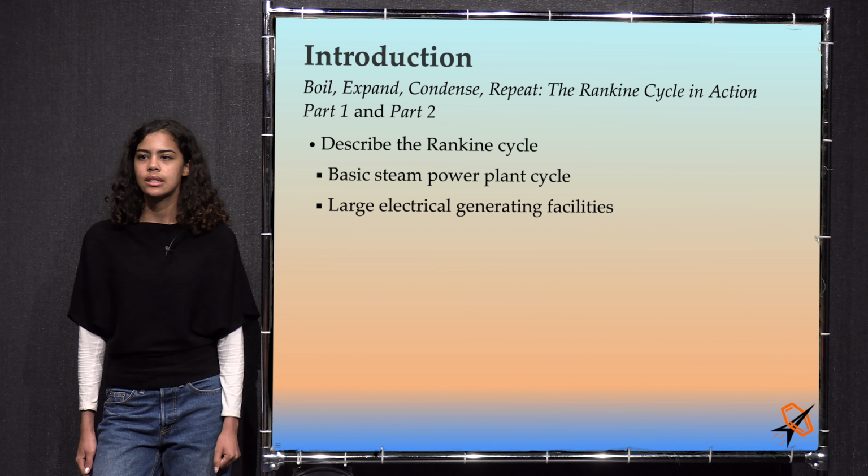So that means the H hat B is going to be the H hat A plus delta H hat. So that's 184.26 plus 8.067. So that's 192.3 kilojoules per kilogram at point B. Next, we analyze the boiler. For the boiler, delta H hat equals Q dot over m dot equals H hat C minus H hat B. And from the things that we've looked up or calculated, that's 3399.4 minus 192.3, or 3207.1 kilojoules per kilogram.